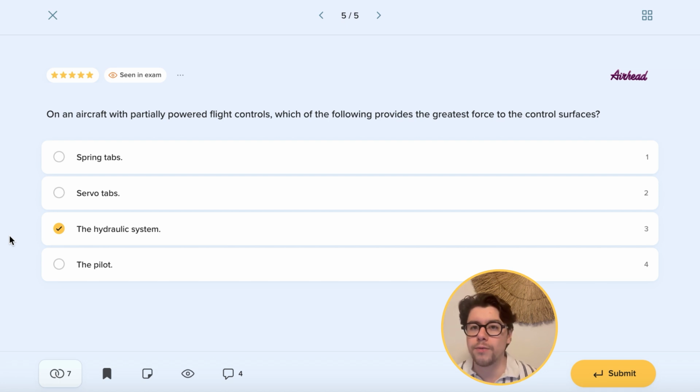And then lastly, we have the fully powered, which we can also divide into the flight-by-wire system, that are both fully powered. The fully powered systems will provide no feedback for the pilots when it comes to the aerodynamics and the movement of the controls and the feeling on the stick. So these are the 3 general systems, with the 4th one being the flight-by-wire, which uses flight computers in order to move the surfaces as the pilot requests the G loading or the roll rates, rather than the specific deflection of the control surfaces.